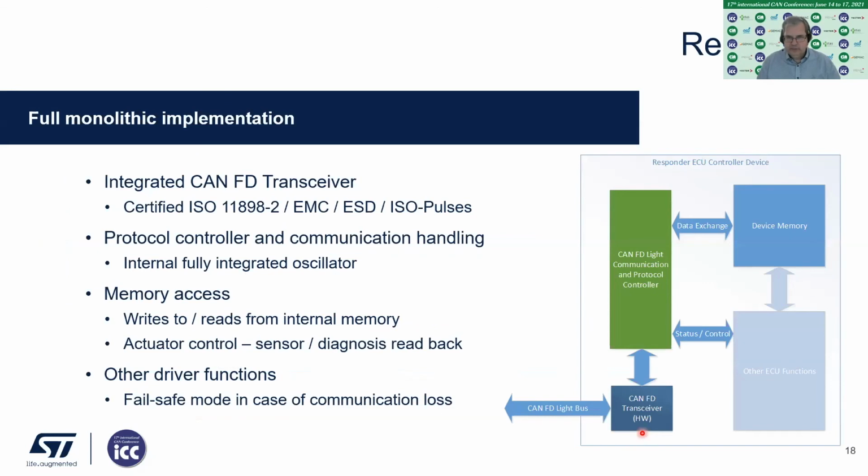This is a full monolithic implementation. We have implemented a CAN-FD transceiver on the device. It's fully certified. Of course, it has to be, otherwise we cannot use it in the network. Then there's a CAN-FD light communication protocol controller with device memory, and some other ECU functions where you obtain status and control. Memory access I just mentioned, so you can write and read internal memory. The oscillator is fully integrated, no external component needed. And in case of a communication loss or other problems, the device enters a predefined fail-safe mode.